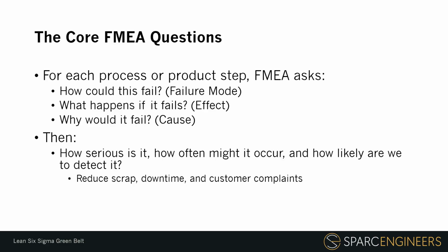First, how could this fail? That is the failure mode. Second, what happens if it fails? That is the effect. Third, why would it fail? That is the cause. After that, we evaluate the risk by asking, how serious is it? How often might it occur? How likely are we to detect it before it escapes?